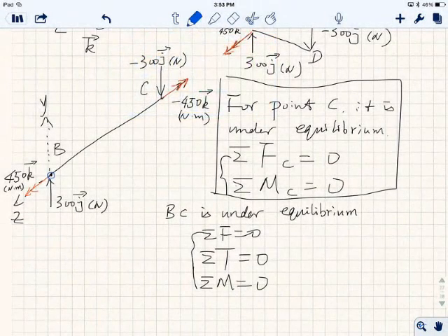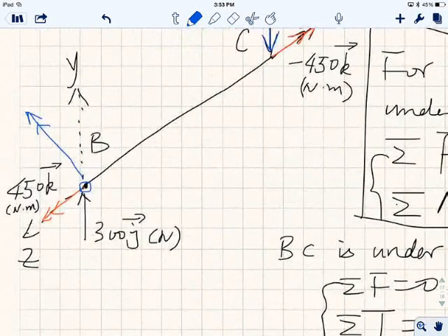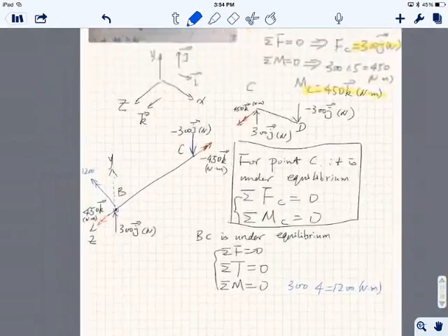This time let's choose blue. This force is going to cause some bending moment at point B in the direction of here. Right? You still use your right hand. 4 fingers going downwards, thumb going back. So that is negative x direction, right? So the magnitude will just equal to 300 times the length of BC, as we mentioned, is 4 meters. So that equals 1200 Newton times meter. So I do the calculation here only on magnitude, as you can see, right? Because directions, I just see from the plot, from the figure, okay? So this is 1200. And this is in the direction of negative I, right? Let me see, yes.